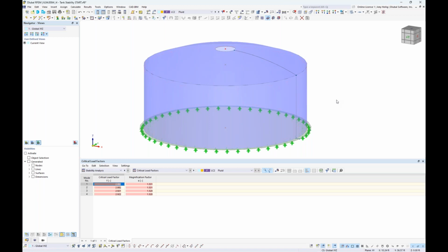But we know in reality that's never the case; there's usually some type of imperfection with the manufacturing and or the installation of these structures. When we refer to the various codes, there are ways to consider these imperfections, and one of them is to directly model the imperfection in our FEA model.